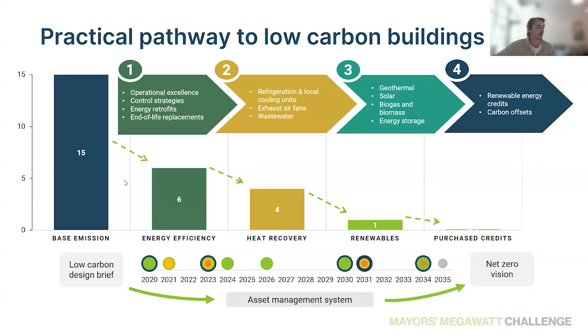Also collect all of the equipment data. That's nameplate photos, reviewing all of the drawings, and understanding how the building is operated and what equipment is being used. From there, it depends on the nature of your brief, whether it's an ASHRAE level 2 or 3 audit or a calibrated energy model. You want some way to qualify and quantify all of that data to get a relatively accurate understanding of how energy is being consumed in the building.